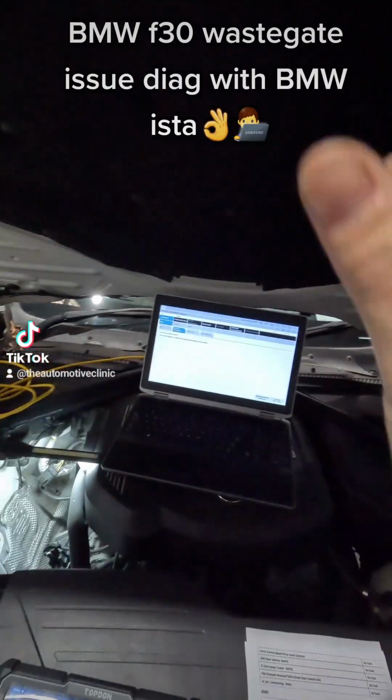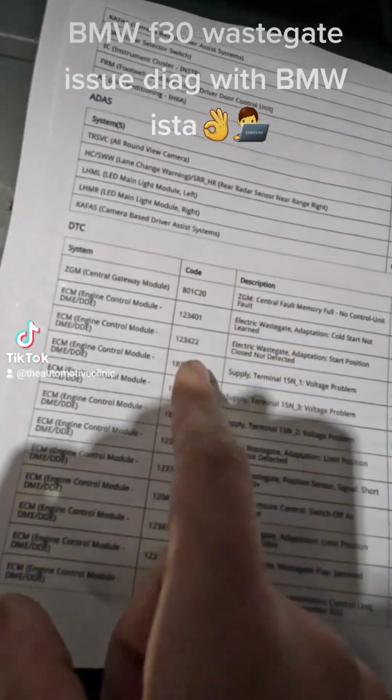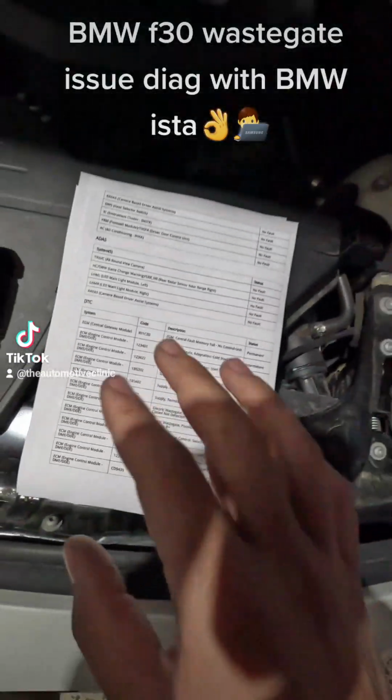Next vehicle we have up is an F chassis BMW. This vehicle's come in with limp mode, check engine light, BMW things. As you can see, we've got 20 faults in the engine computer, and the main one that we're concerned about is these electronic wastegate adaptions, cold start not learned. This is what the shop's brought it in for.